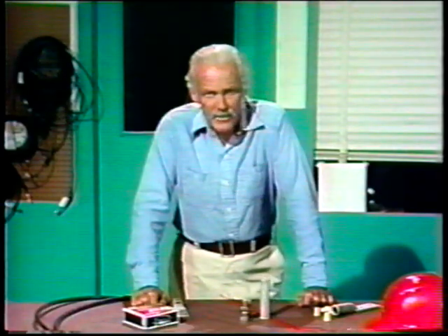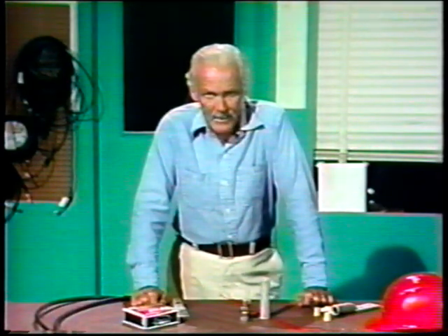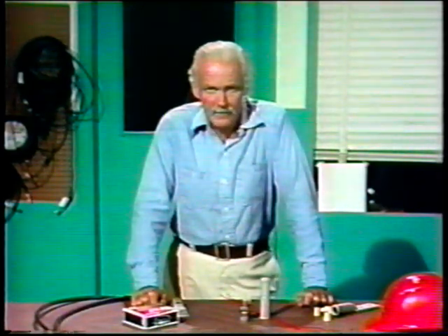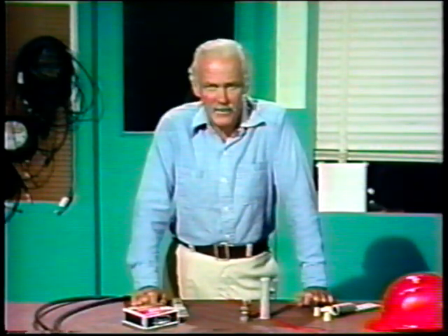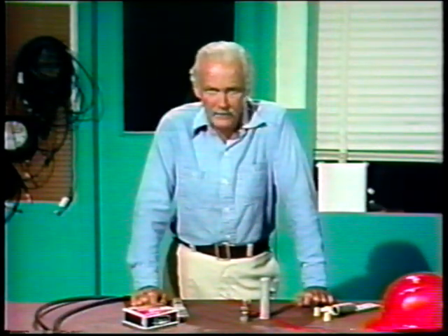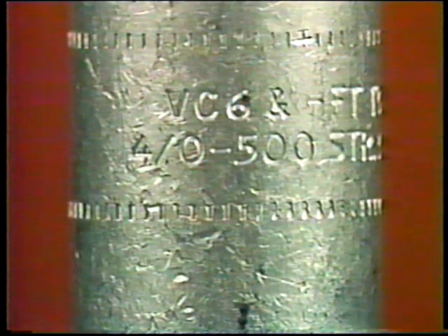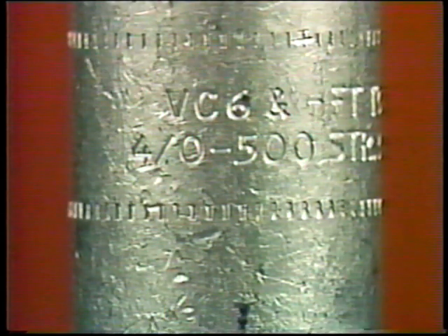You have to base your decision on two things: size and metal. The size of the conductors you're splicing together and the type of metal the conductors are made of. On most connectors, you'll see either a size or a range of sizes stamped on the metal. And in addition to that, you may find information that specifies the type of metal the device is suitable for.